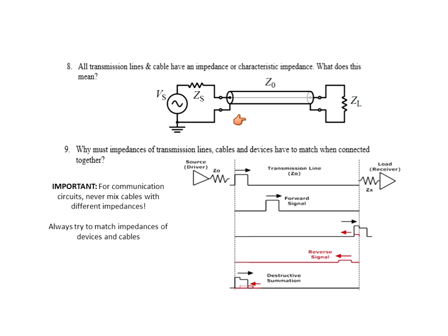So every transmission line has an impedance. What does that mean? That is the number of ohms in reactance and resistance that the signal sees when going into or leaving the cable. So a transmission line acts like a circuit. We have to treat it as such. That transmission line or twisted pair or coaxial cable will have an impedance. That impedance is very, very important. What is the impedance of that cable? It's what the AC signal sees when trying to get in or leaving the cable.